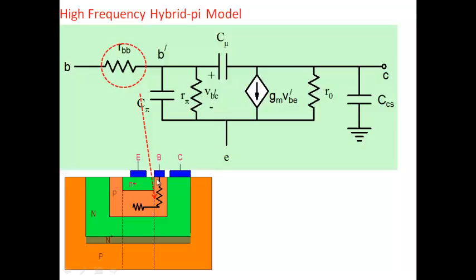So far when we wrote all that, we didn't bother about how the current goes from the base terminal and reaches the junction. This is the junction here. We didn't talk about it because we had a one-dimensional schematic. But note that as the current flows from here and comes here, all this P region is nothing but a resistor. So there is a bit of resistance between this terminal and the junction, and that's the resistance we've added, this additional resistance RBB. At some places, especially in high frequency analysis, this RBB becomes important and we need to include it. So that's the origin of this one here.